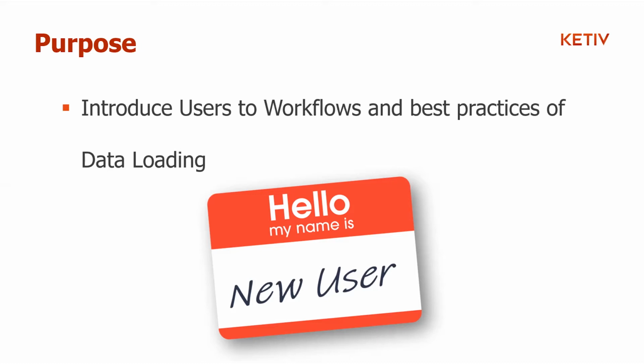The nice thing is, when you draw that line in the sand, if there is an archive project, typically what you can do is use either the autoloader or the task scheduler to load that into the vault when necessary. Let's say a customer requests it and you do need to make changes to it. You can just go ahead and load that into the vault without any issues.